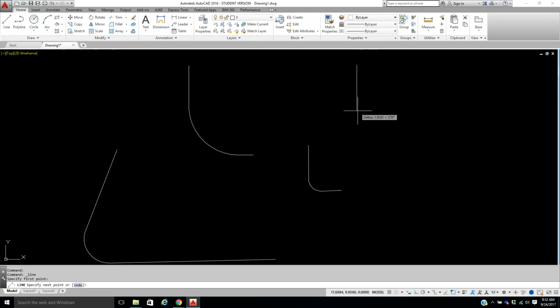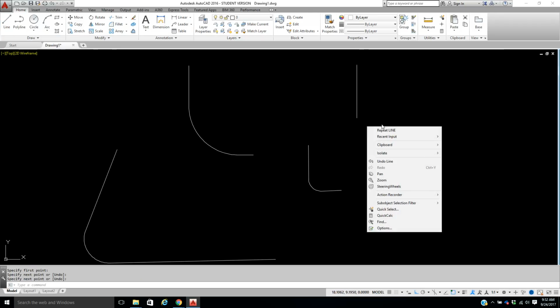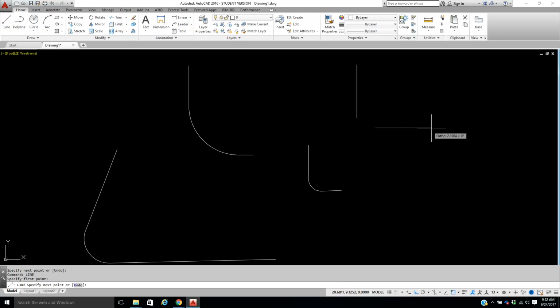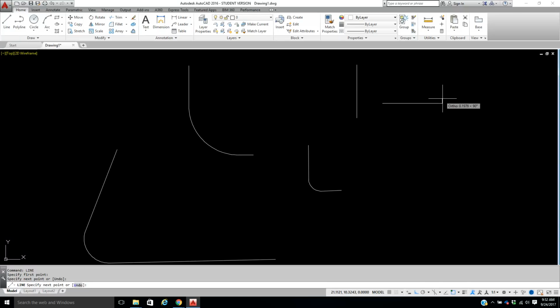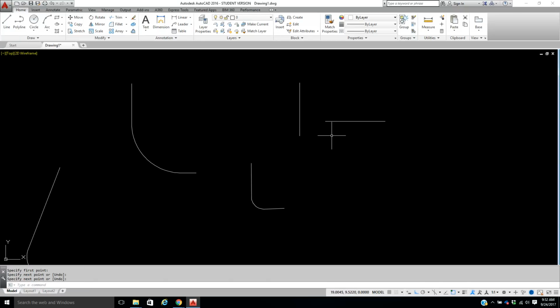Once again, when you have lines, what I want you to start getting away from, let me move this one up so you can see, is if you had to close these 2 lines here, what a lot of people do is they will come in and they'll say, oh, I'll just take a line here and I'll bring this out to here, and then I'll come back and I'll do this trim like this, and you can trim it all up. Well, the problem is now you got 2 separate lines, and that's not good for your drawing. It can really mess you up later on.